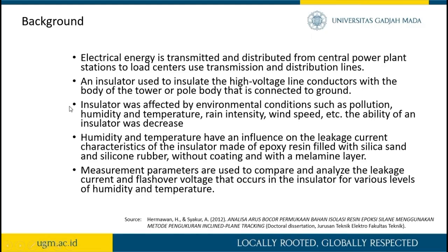The ability of an insulator decreases because of that. Humidity and temperature have an effect on the leakage current characteristic of the insulator made of epoxy resin filled with silica sand and silicone rubber, without coating and with a melamine layer.